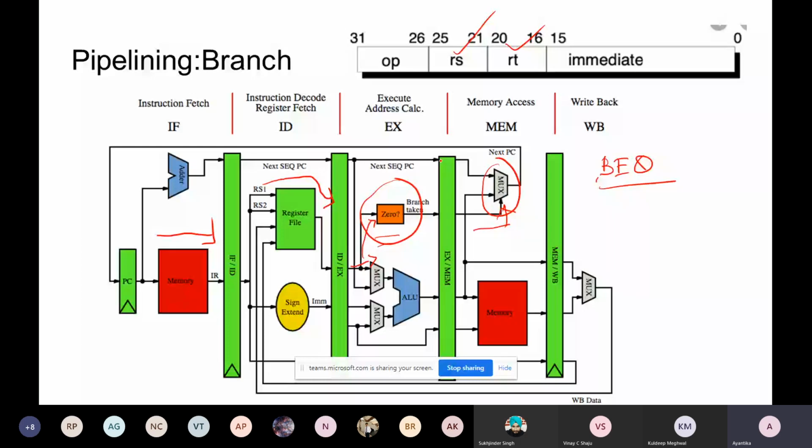See, when we do general execution, I have written defined: add this, subtract this, multiply this, one by one. So what my PC, the program counter, does is it immediately goes to the next instruction. How does it go? See, here this is the program counter. With that program counter, there is an adder. One input of PC goes to this adder, and another input takes the value of +4, generally +4 in this case. That, if I go for the memory structure of it, is the location of our next